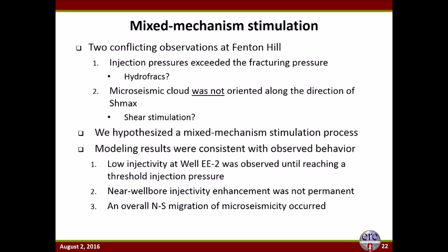Specifically, there was low injectivity at one of the wells up until reaching a critical threshold pressure. And this was consistent over multiple stimulation treatments in the well. But in fact, that near wellbore injectivity enhancement was not permanent. And then, like I said before, the overall migration of the seismicity at the site was not aligned with the direction of the maximum principal stress.